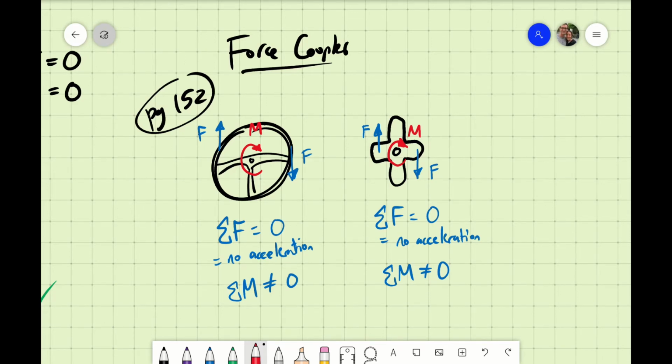And he also points out in this case, to get the magnitude of the moment, you should use this distance. Just use that total gap between the two forces and then multiply that times one of those forces, not both, just one. The moment in this case is force times distance, just as it always is. But we're not adding those two forces together. We're just picking one of them and multiplying it by that total distance gap between them. They are still perpendicular. Everywhere you look, things are still perpendicular. So we're being very consistent with all that we're doing.